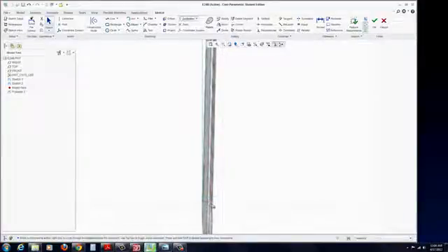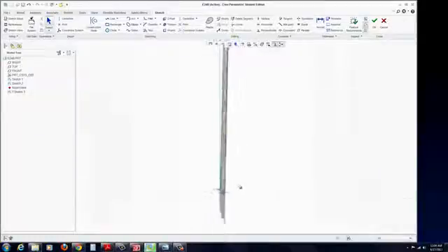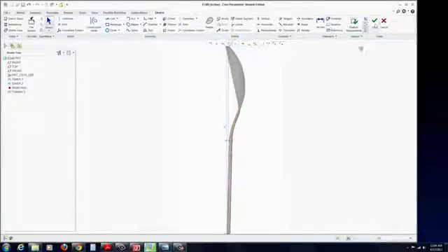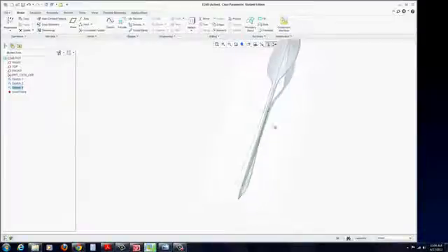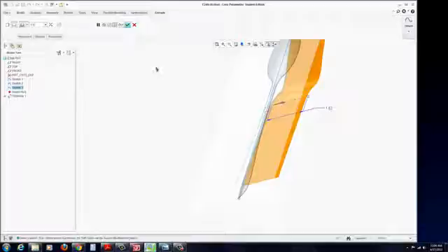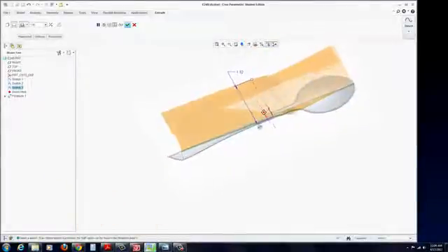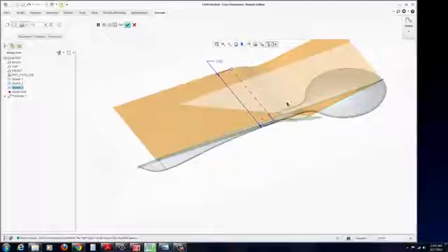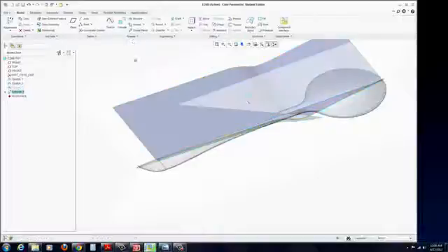And again, if you want to use a center line to constrain this tangent so it's vertical, not a bad idea. Come out smoother then, once we add some constraints on our blend that we'll put in at the end. Okay, hit the green check mark. Okay. Now we can take that. We're going to use that curve that we just drew as our tool here. We're going to extrude it, flip it so it actually goes underneath the curve that we drew on the side there. As long as it goes beyond that curve, you're in good shape.